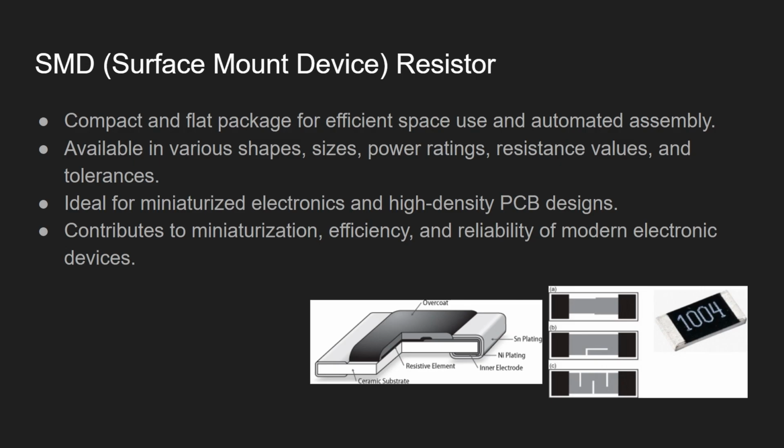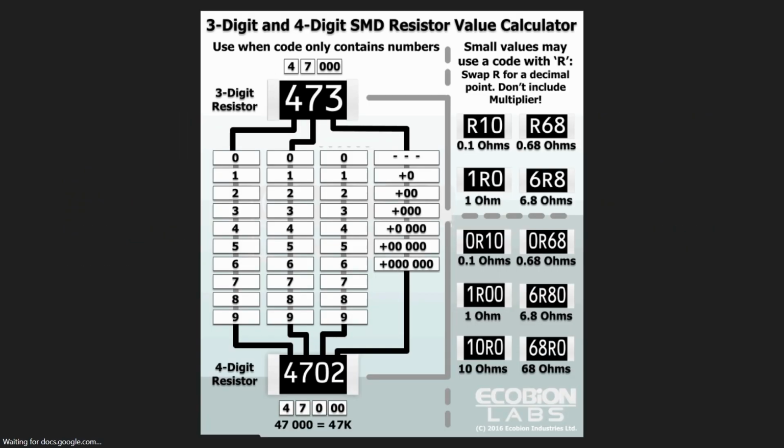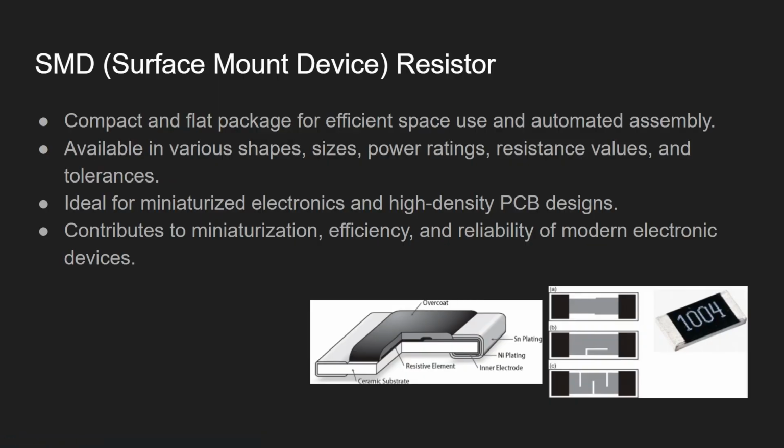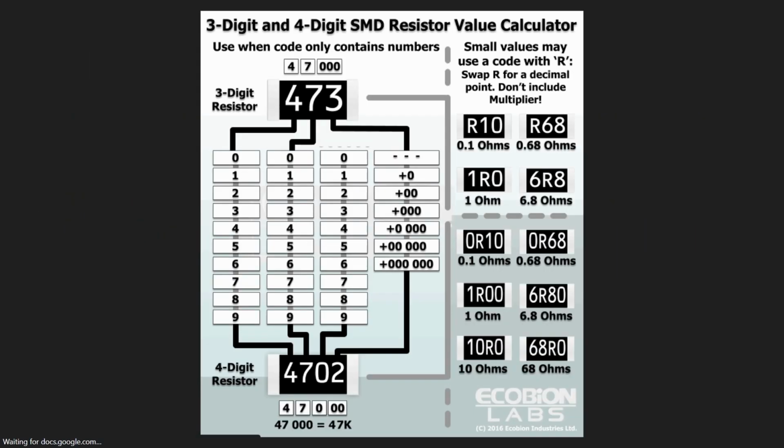It is a common type of resistor on PCB. You see that there is an example here, right? They cut the metal wire so that it is a thinner and longer track, so it could control the resistance. And for this one, it makes it narrower, so it helps to control how large the resistance is.